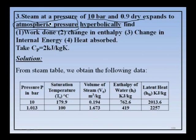So, the value of atmospheric pressure, see here in the steam table, is 1.013 bar. Sometimes they do not give the values, they just say something like 2 atmospheres. In that case, you should take the value of pressure as 1.013 bar. Okay, next, the process is given as hyperbolic. You should find 4 parameters: work done, change in enthalpy, change in internal energy, and heat absorbed.